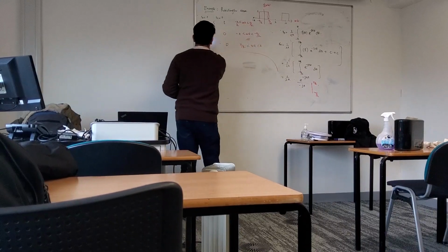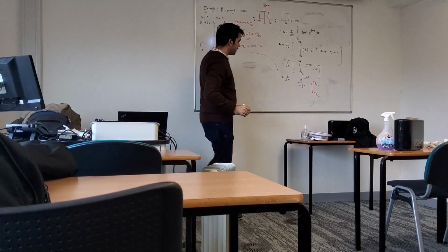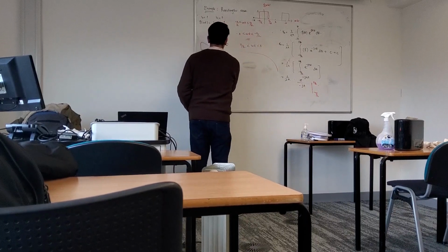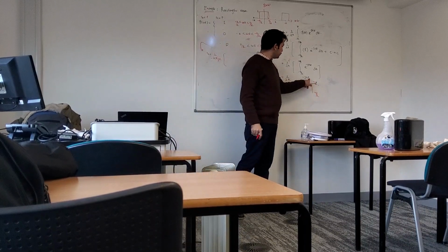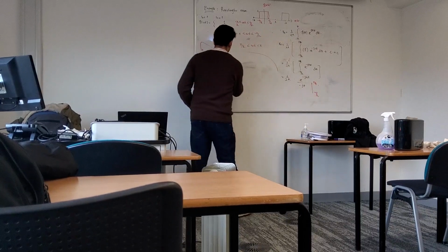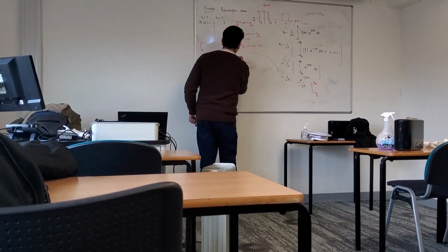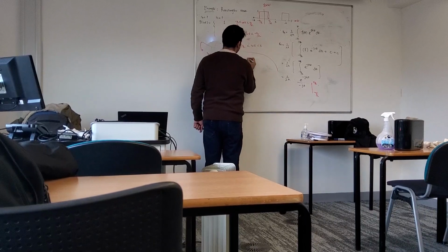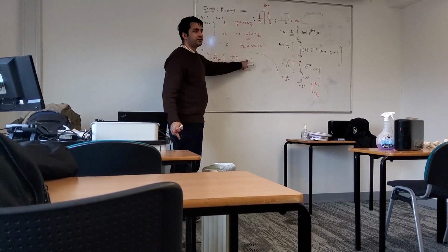I will further solve it here. So Rn equals 1 by 2 pi. Since there is no limit in this term, I can take it outside, 2 pi jn, and inside I can apply the limits. The upper limit goes in place of theta, so e power minus j n, and in the place of theta I can write pi divided by k. Similarly, minus the lower limit e power minus j n, and since there is another minus, this minus will become plus.